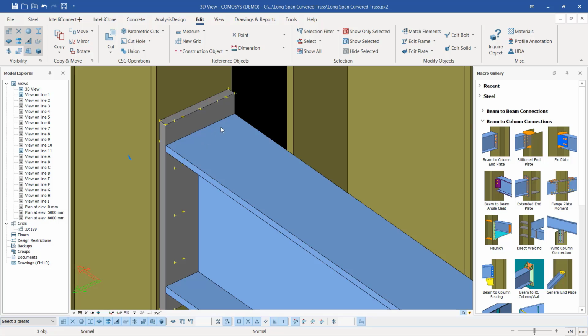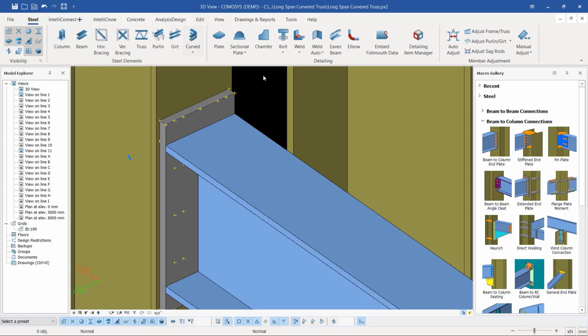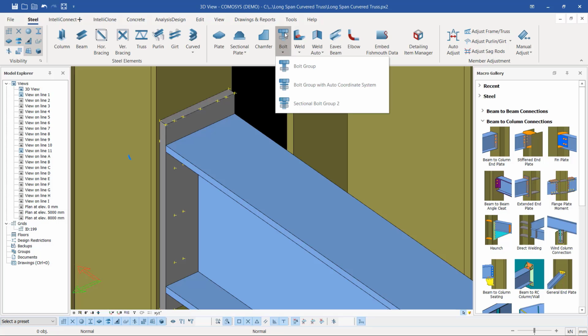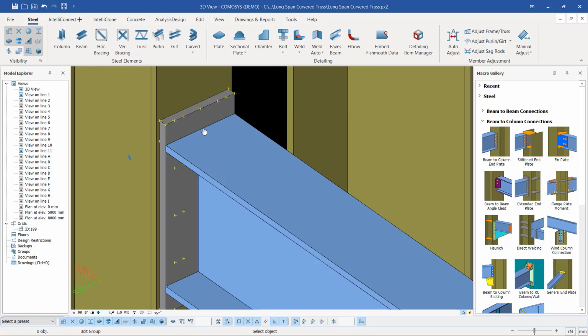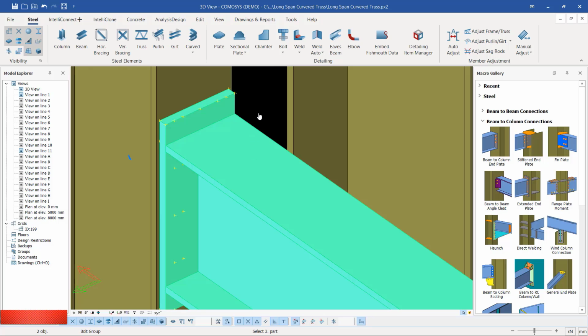Now the next thing, I want to weld this beam to this plate. Prior to that, let's first create a bolt between this plate and the column. To get the bolting tool, I'll come to steel here and come to bolts. I'll click on the bolts, select this plate and this beam, and right click to make the tool active. So I have 2 points to place my bolts. I have three, point 1, point 2 and point 3.